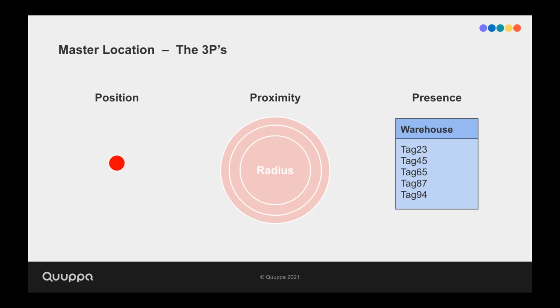Now the QPE will basically give you the best estimate of where that tag may be, even if we don't know its exact location. Taking the example of this proximity location, let's say that our environment is such that there are a lot of metallic objects causing reflections, and this affects the accuracy of the locator reading the tag, i.e. the same tag is being picked up by multiple locators or in multiple locations. As we can't tell the exact location of the tag, the QPE will now deduce the location of that specific tag based on its RSSI value or power output.